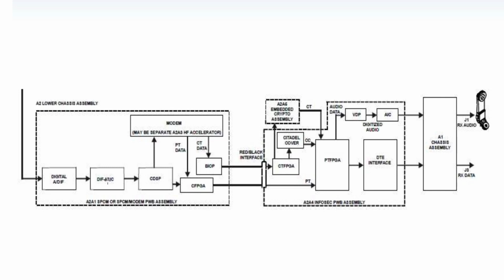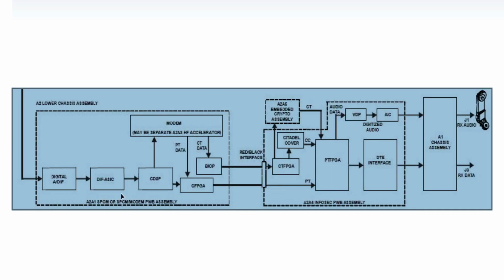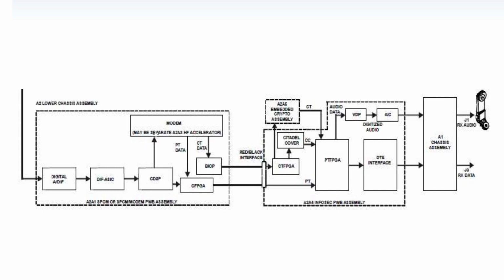It's going to keep that. Instead, it's going to take that analog that was digital originally and put it back to digital, or keep it at digital. So it's just going to modulate that 240 kilohertz, the IF. It's going to extract it back out, send it through. If it's plain text, it'll just go through the bottom here. If it is data, or ciphertext or CC, it'll have to go through the modem. If not, it'll just come through the bottom.